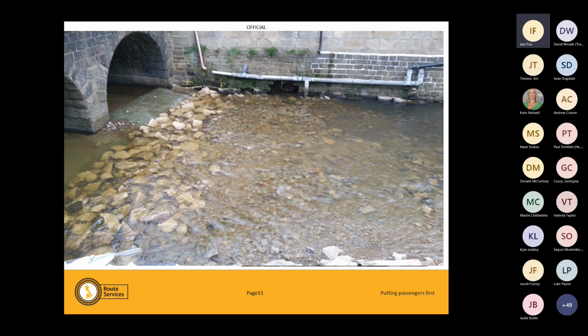That's great. We've got a concrete invert, a hard invert through our structure and out in the estuary. Brilliant. What we don't have is what's called a transition material under here. And all of this hole that you can see is actually a scour hole caused by a poorly designed scour protection scheme. Now, in the top of it, you think, that's fine, we've got a concrete invert, but look at the damage it's caused downstream. That is a Welsh Water supply pipe, and that is currently just dangling there.